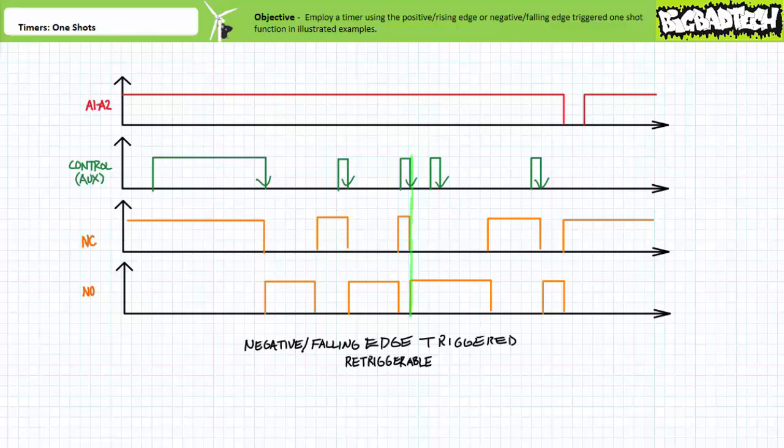As previously, the only real difference is when this retriggerable OneShot experiences a triggering event followed by another triggering event during an ongoing OneShot. The retriggerable OneShot, instead of ignoring the additional input, basically extends the OneShot as we'd expect. As previously, if the timer ever lost power during an ongoing OneShot, the ongoing OneShot would be canceled and reset, and all associated contacts would immediately return to the deactivated state. The restoration of power returns the timer to service.